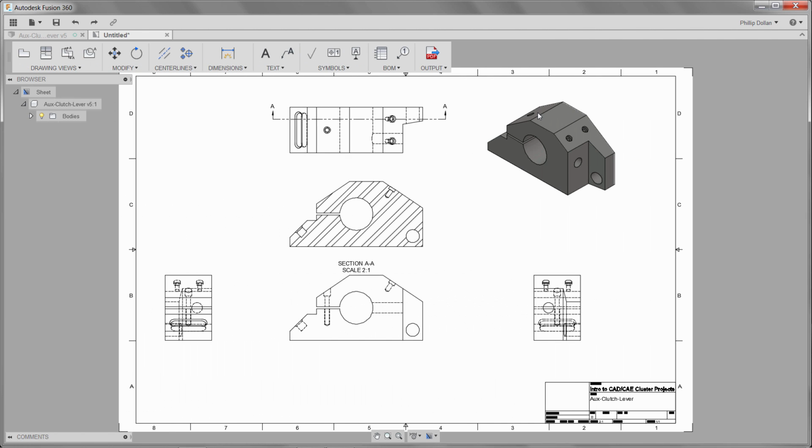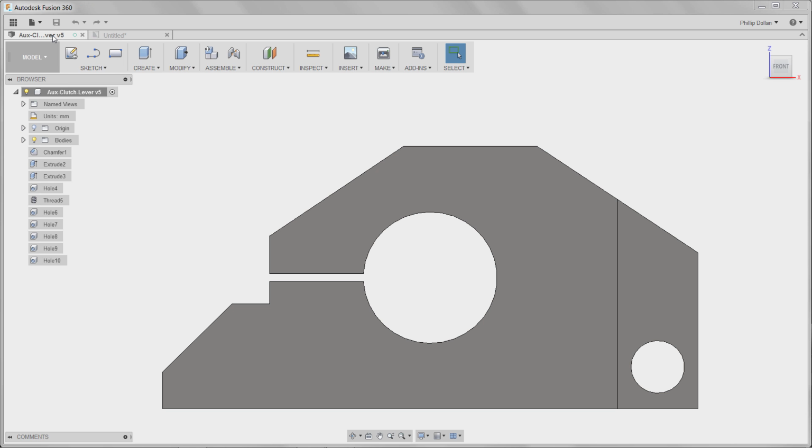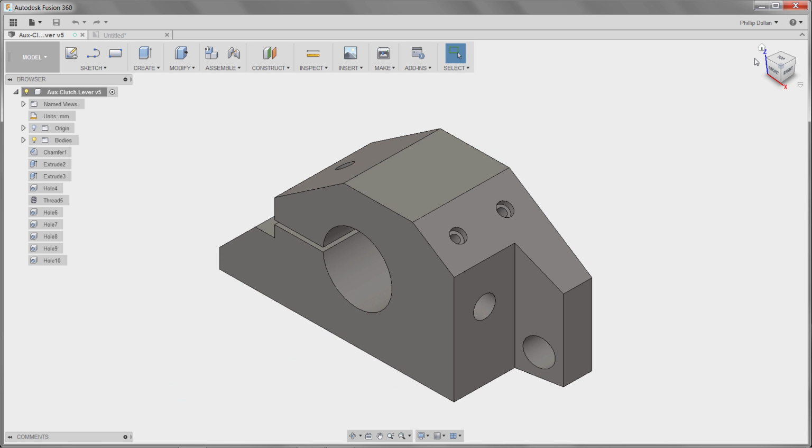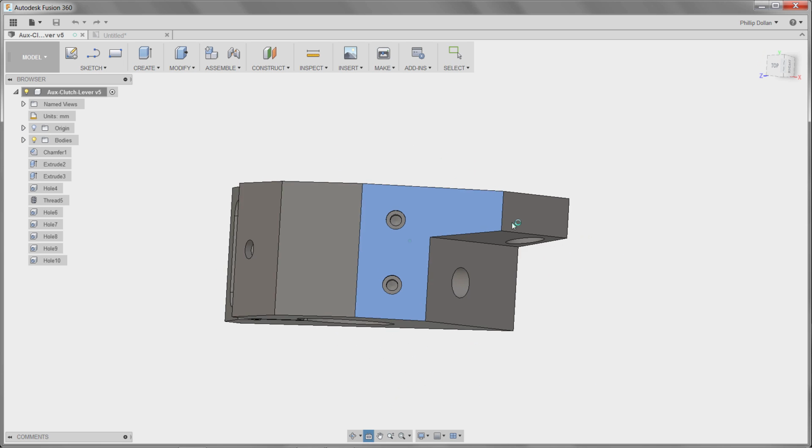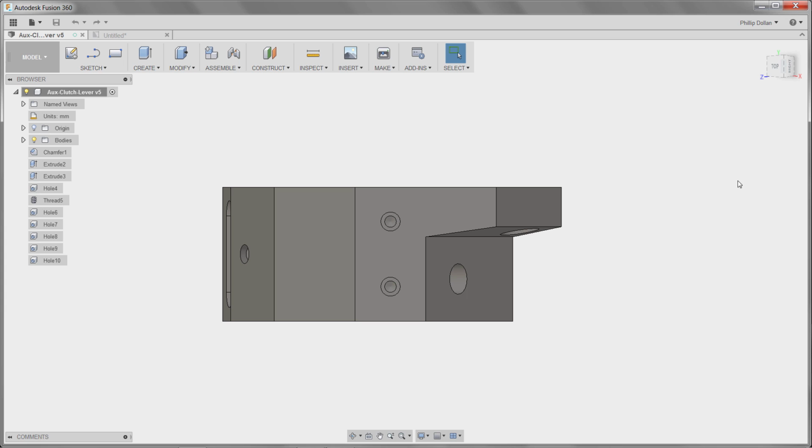There are a couple of sloping faces. I'm going to have to create true shapes of those. To do that, I'm going to go back to the part, and then temporarily create a new top view. So let's look at one of the faces by going to Look At, select the face, back up to the view cube, right-click, and set that current view as top.